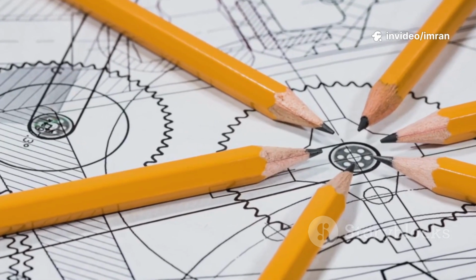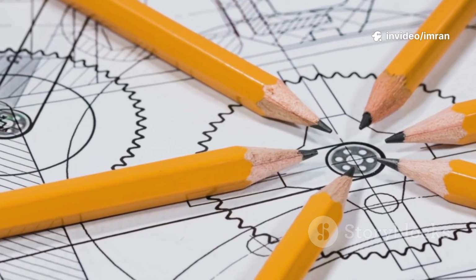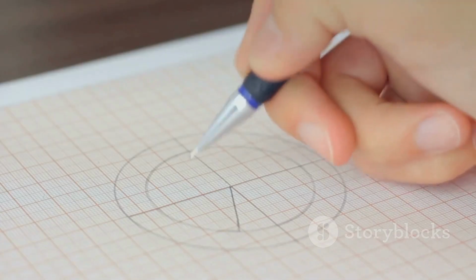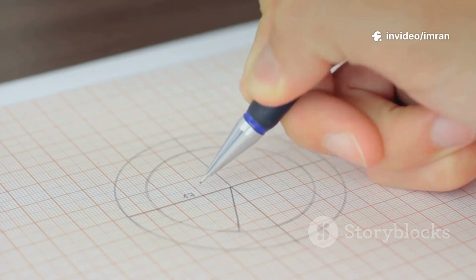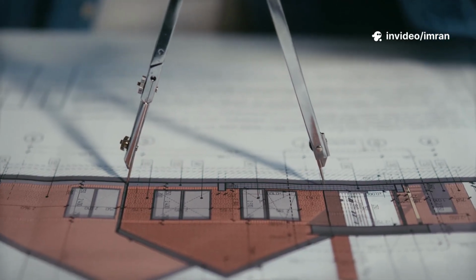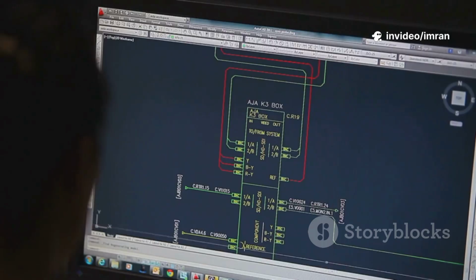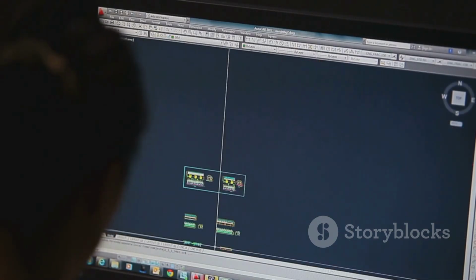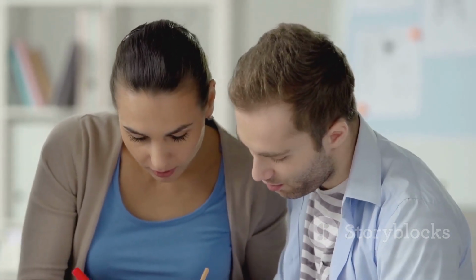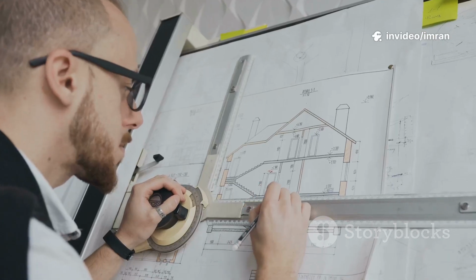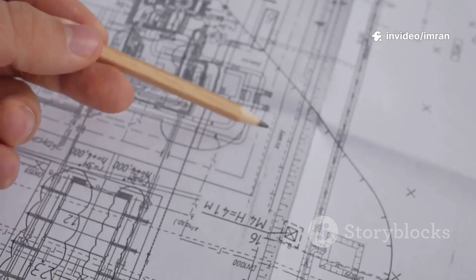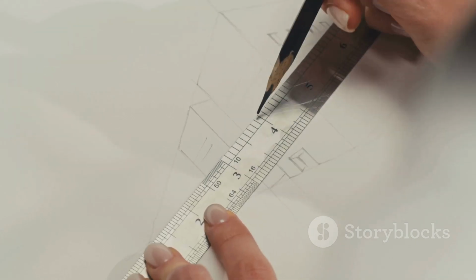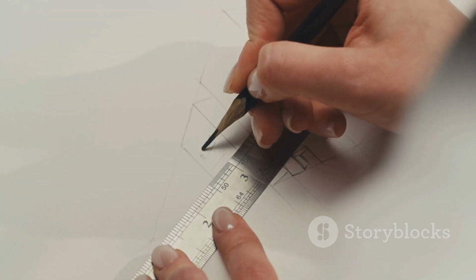Beyond common shapes, AutoCAD offers tools for complex geometry like ellipses and polylines. An ellipse, a flattened circle, is often used for isometric drawings. Access the ellipse command from the Draw panel or by typing EL. Define an ellipse by its center and axis endpoints for precise control. The polyline, a versatile tool, creates a single object from connected lines or arcs. Accessed with the PL command, it simplifies selection and modification. Calculate length or area with a single click. While drawing, switch between lines and arcs and specify segment width. Mastering polylines allows intelligent and editable geometry.